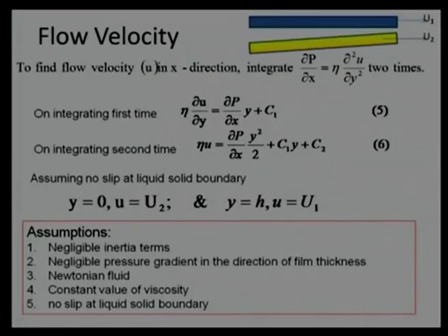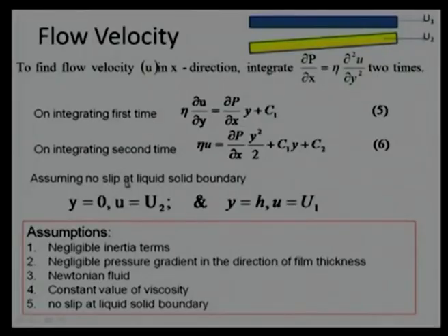If we use some kind of slip condition, then the expression will change. For most liquid cases this assumption is justified, but this will be a problem particularly in gaseous lubrication. In gaseous lubrication there will be some slippage which needs to be considered. Many times we say first order slip, second order slip, that can be considered when we develop this equation for air bearings or gas bearings, right.